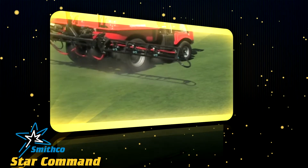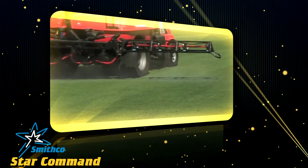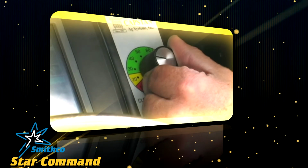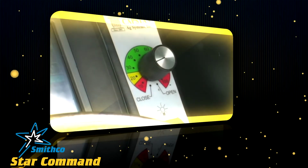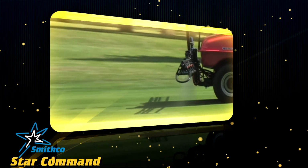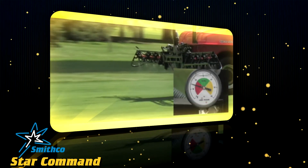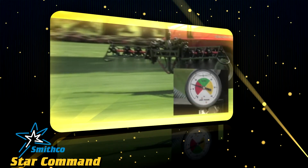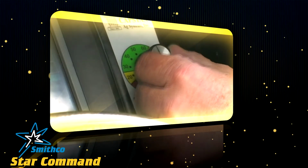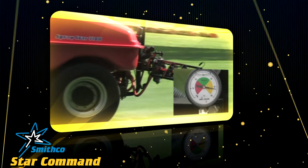Sharpshooter utilizes drift reduction tips, but also affords the operator further on-the-go drift control. The operator simply dials the Sharpshooter control to a lower pressure. The operator-selected lower pressure provides bigger droplets and fewer driftable fines. The application rate and speed are maintained independent of this pressure change. Once the drift concern is passed, the operator can dial the pressure back to the original pressure set point for optimum efficiency.